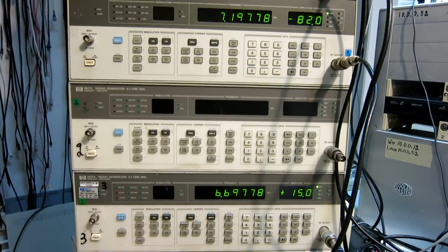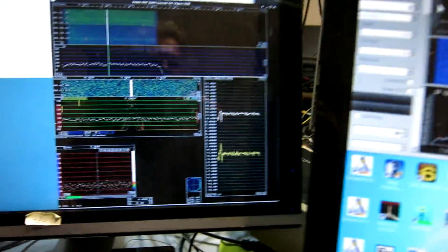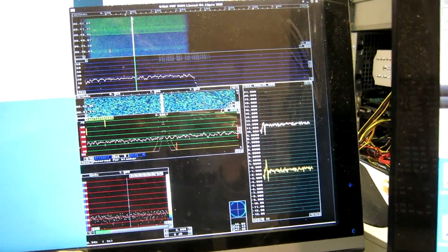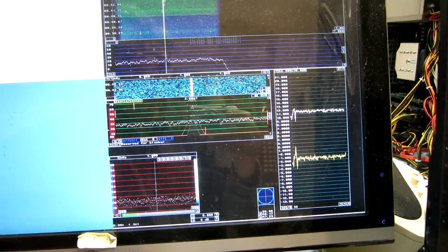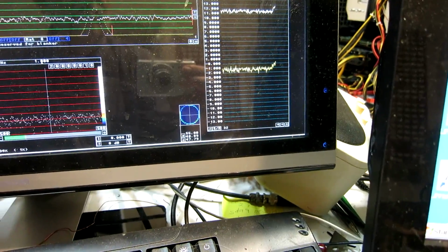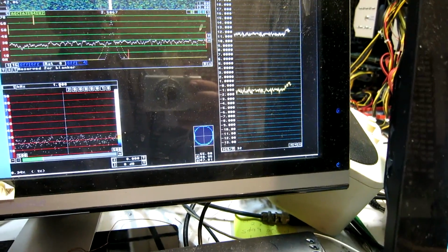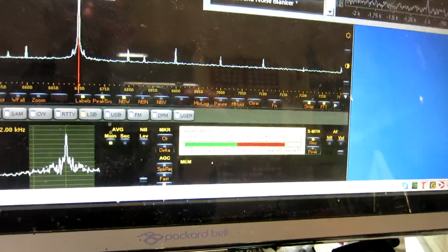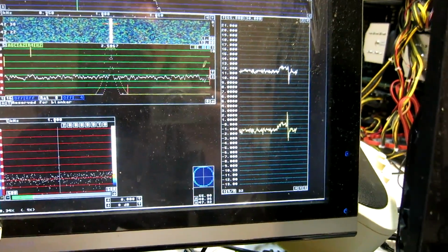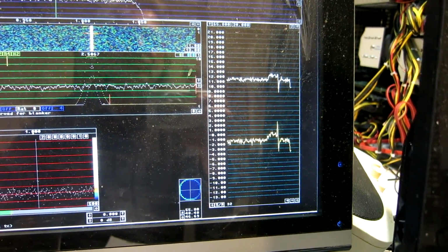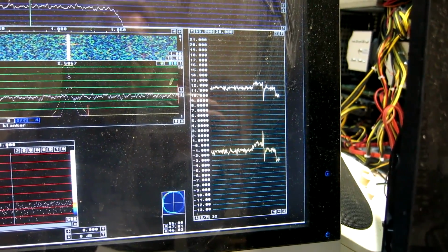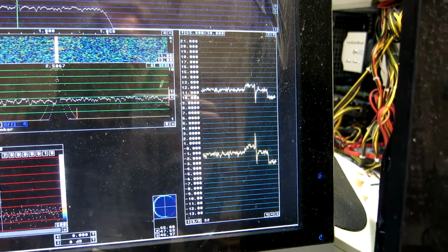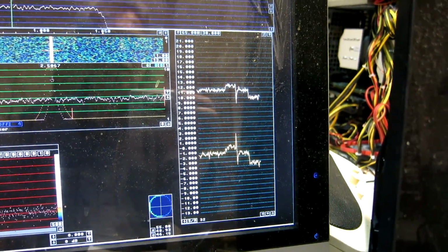Now the signal is 0.5 megahertz below. I'm running the 1633 and I have a modest degradation, as I can show by switching off that strong signal. It is about 1 dB. So I put the strong signal back. The level is minus 19 dBm and I increase by 1 dB. As you can see, I am losing 2 dB of signal to noise ratio and I have more than 3 dB loss. So I turn it back 1 dB.